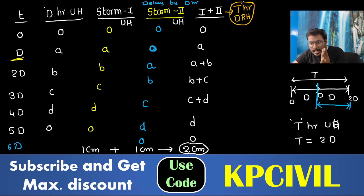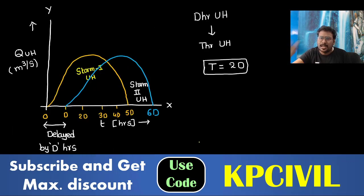You have added storm 1 of D hours and storm 2 of D hours. Total 2D hours, 0 to 2D. That is the T hours. Storm 1 of 1 centimeter, storm 2 of 1 centimeter, total 2 centimeter depth. It is not 1 centimeter depth, so it is a DRH, direct runoff hydrograph.